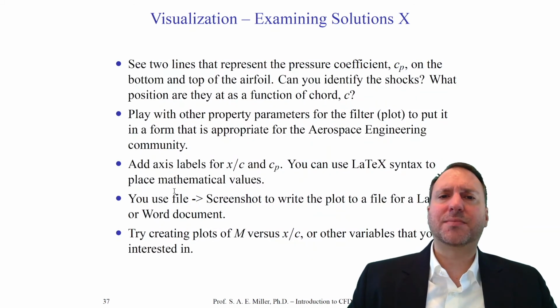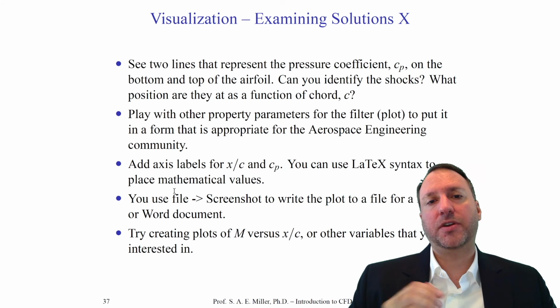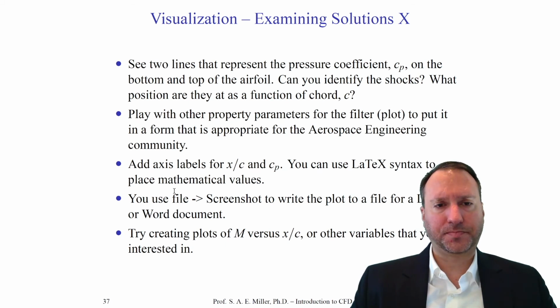You might ask, why is Mach number non-zero on the airfoil surface? Of course, in reality, the flow will be 0 at the airfoil surface because of the no-slip condition. But remember, our boundary condition was a slip condition Euler, which we specified in the configuration file. We could easily rerun the code with a no-slip condition and get a more accurate solution.